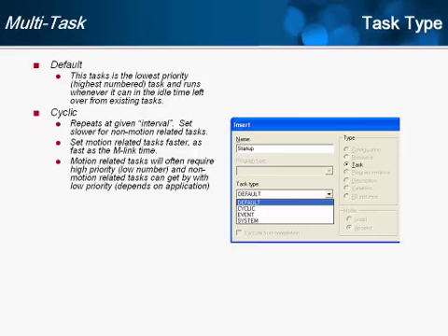And once you choose the cyclic type, you can set this interval. Cyclic tasks are what you'll use to run the bulk of your machine code. And so you can put POUs that run the most critical part of the code, such as the motion blocks, into the fastest tasks, and the less critical code, such as user interface, could run in the slower tasks. And additionally, we'll see later, you can set the order in which the tasks run, which often will mean that the fast motion related tasks, you want those to run first. And I'll be doing an example of a fast cyclic task after I finish up this startup